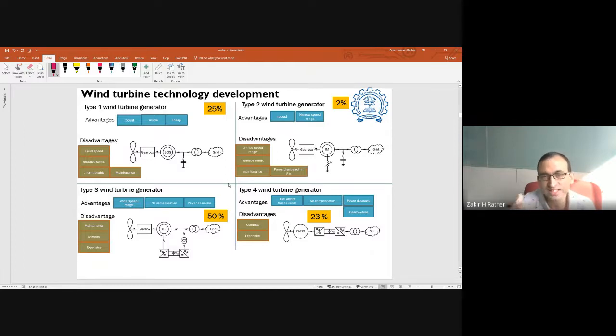And as a result, it will release instantly some additional power to the grid from the rotating mass of the machine. This happens inherently, but more important, instantly. It is just at the onset of the disturbance, it immediately releases additional energy to the grid. We'll understand why it is important in a few slides down.